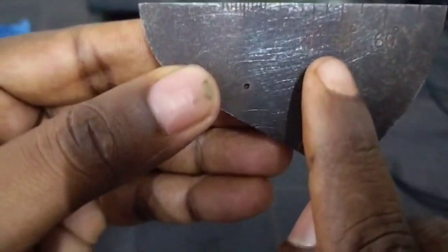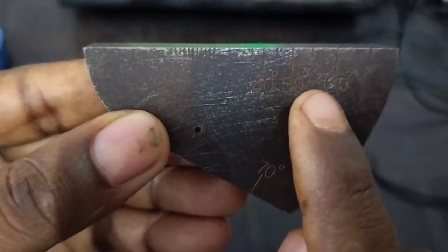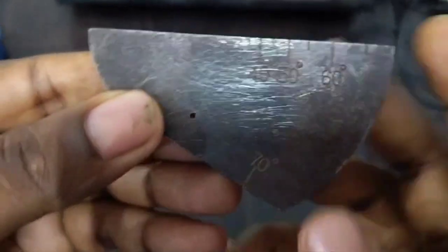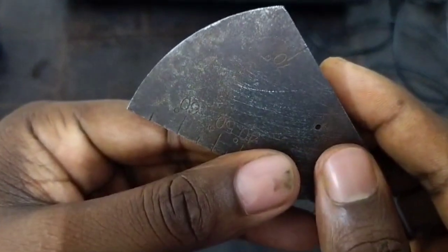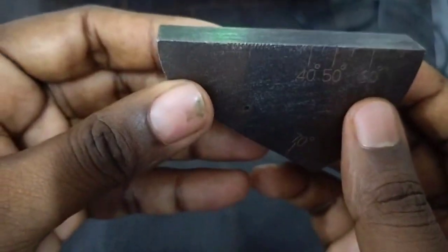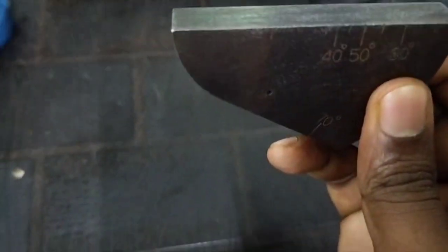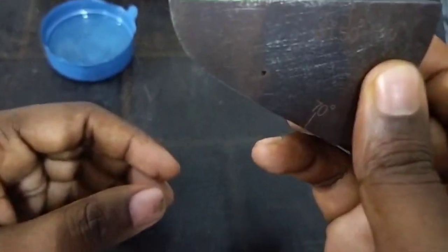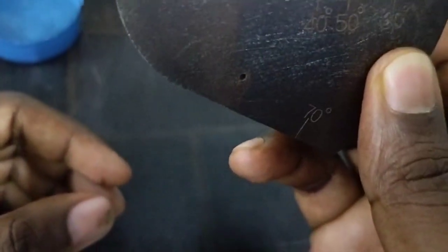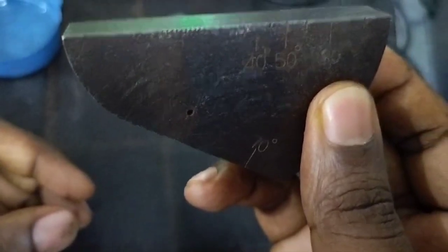Here are the angles which are engraved into the V2 block, that means 45 degree, 50 degree and 60 degree. When we put the probe exactly at the top of the V2 block, and the beam index point is perpendicular with that particular angle, it will perpendicularly strike the 1.5 mm side drill hole, which is exactly 19 mm in depth.